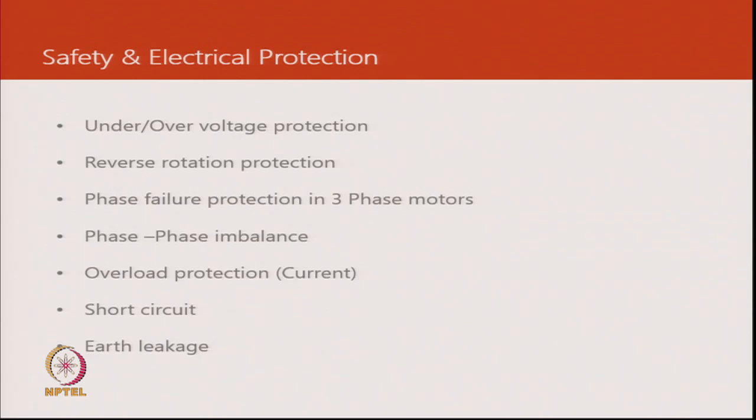And phase failure, the case study that we did, railways had this component so that the phase-to-phase imbalance is not leading to compressor failures. Again, these are all costs that we are undertaking so that we protect the most expensive part of the air conditioner. Overload protection through overload relays, and then there could be electronic relays. Short circuit is, both options are used. A fuse, in residential products you will notice a fuse which is only for the control part. In commercial you will see MCBs and even MCCBs to protect the compressor.